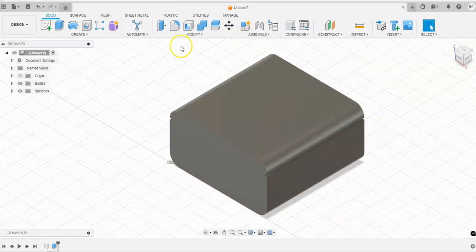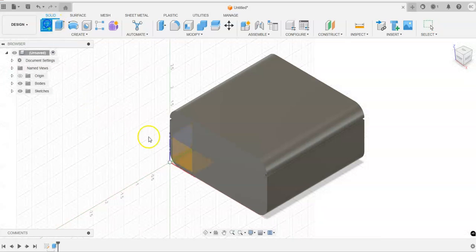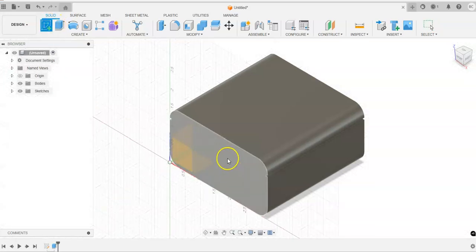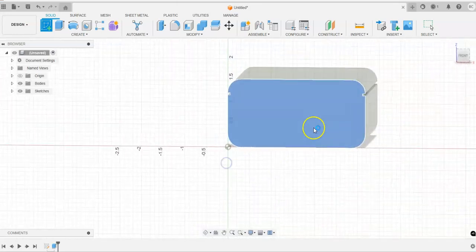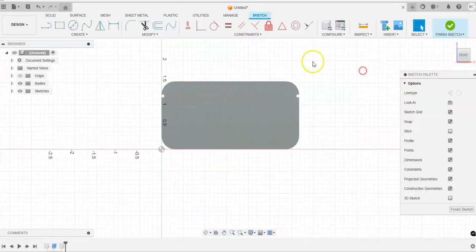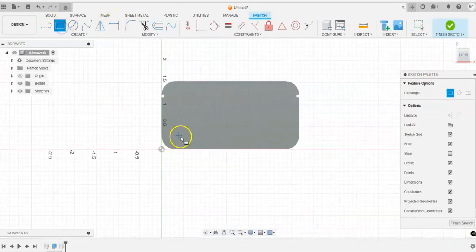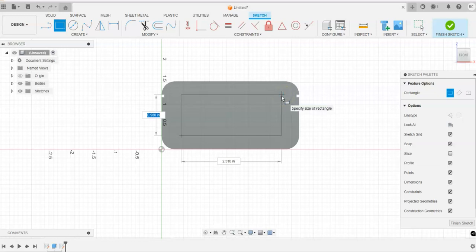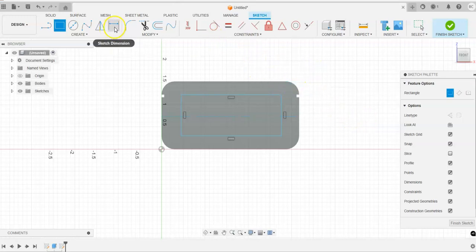So now I'm going to create the geometry on the inside of this front face. We'll go right back to our different rectangle tools here, and again, I'm not too concerned. If you want to go ahead and put the dimensions in now, you can, but we can dimensionally constrain this the way it is shown on the actual print to get everything in.